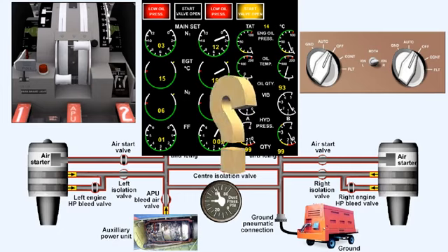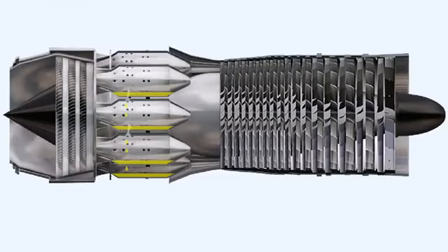However, it may be some time before it's realized that there is a problem, and that the problem is a wet start. Starting malfunctions on gas turbine engines are rare and always come as a surprise, except in the flight simulator, where they tend to become the norm. Thus, there can be a long period during which fuel is being pumped into the engine before the problem becomes apparent.